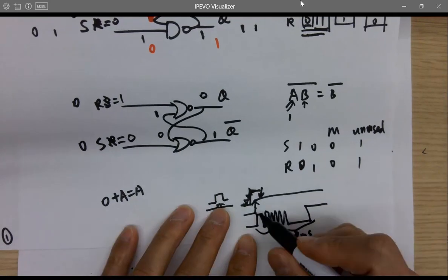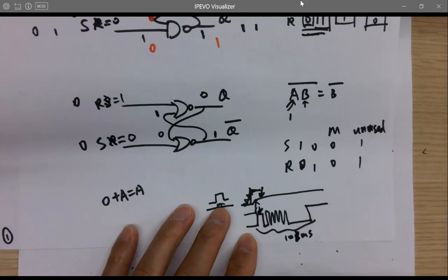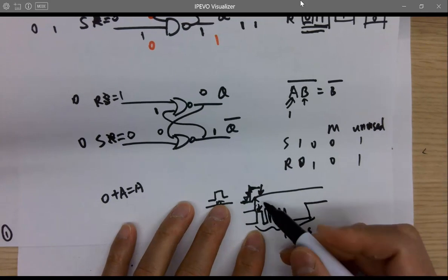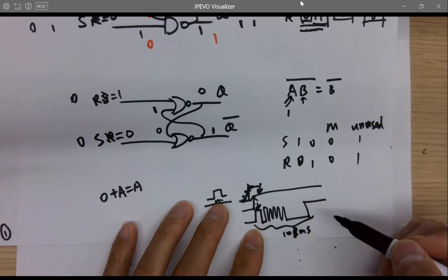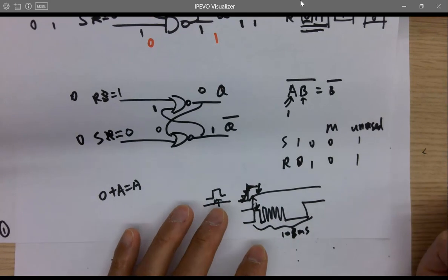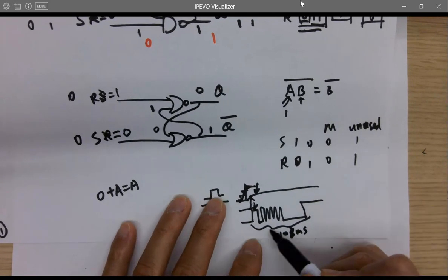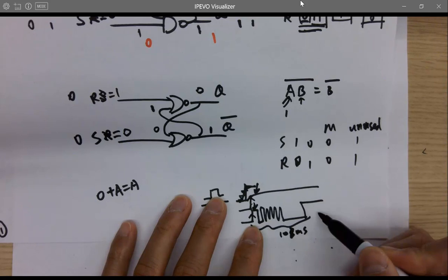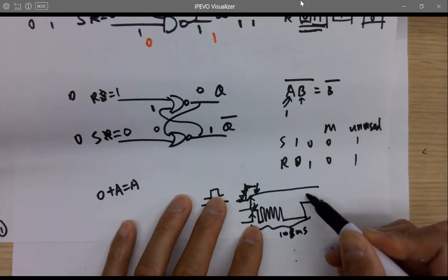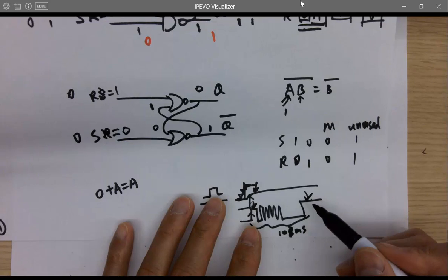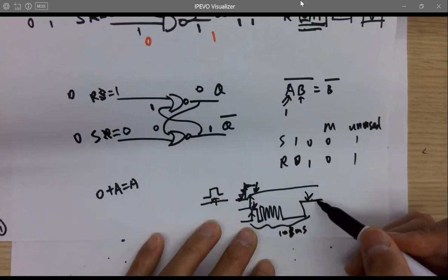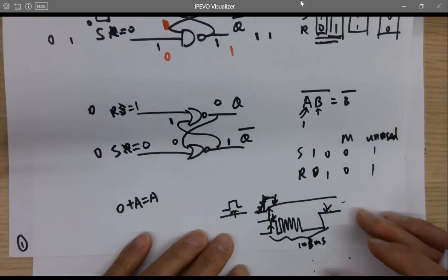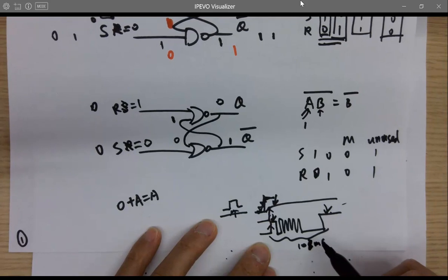So in that case, it detects if the voltage is high, you do something, and then the voltage becomes low really quickly. So you're actually making it super inaccurate for the software, because software can run really fast. And you want to have a time delay, right? You press it, you detect a change, then you start a timer, okay, until a certain time delay, you detect that again. If it's still high, which means somebody really pushed the push button, then we'll just execute the following code over there. So that's debounce. You can do debounce by adding a time delay in C++, okay?